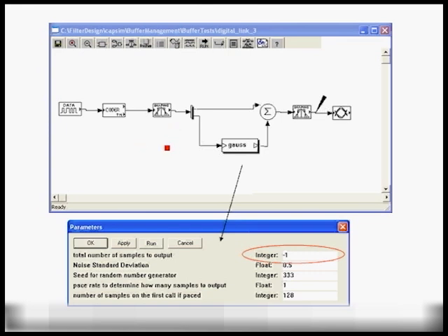Many times in Capsim we simulate, for example, fiber optic links in which we generate gigabits of data in order to get the bit error rate with no problem at all. In Capsim simulations with multi-rate signal processing, you can simulate billions and billions of bits with no issues at all. And because each block basically consumes all its input samples and runs on a per call basis, we have very efficient simulations.